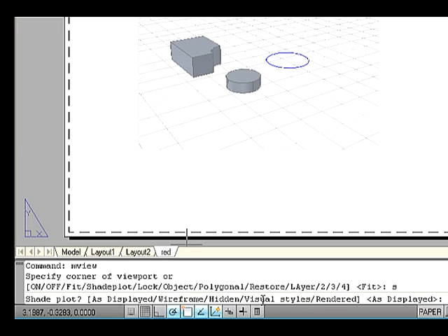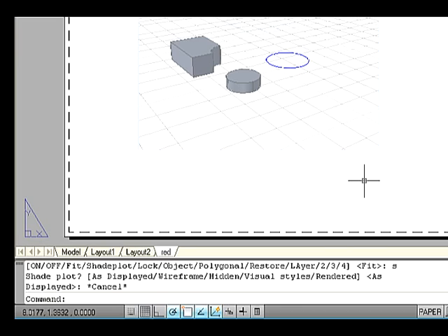All Visual Styles specifies that a viewport is plotted using the specified visual style. All visual styles in the drawing are listed, whether the options are in use or not. All Render Presets specifies that a viewport is plotted using the specified render preset. All render presets are listed as options. Now select any one option. For example, select Hidden and press Enter. These changes are viewed only when plotting or plot preview is on.